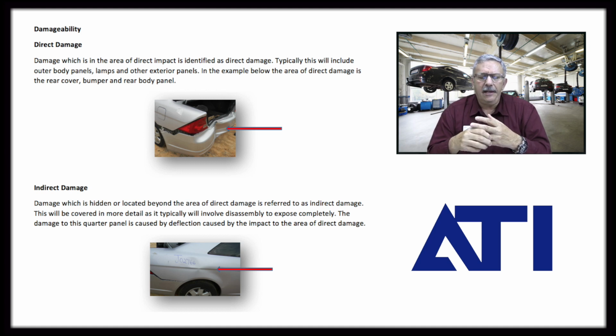One of the things that you have with welded panels that's important to know is if you are going to weld a panel in place, you're supposed to do a test weld. So you're supposed to do 2 tabs of the same material that you're going to be welding into the vehicle. You do a test weld and you do a destructive test to make sure that the weld nugget pulls away from the part that was welded, or the 2 parts that were welded together.